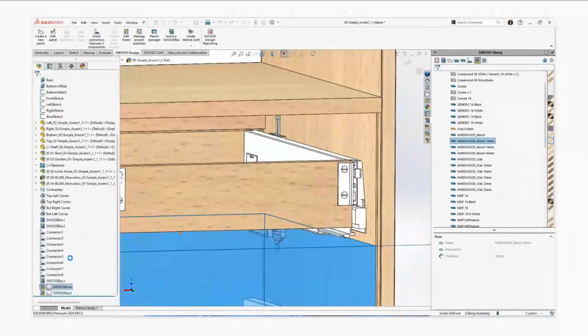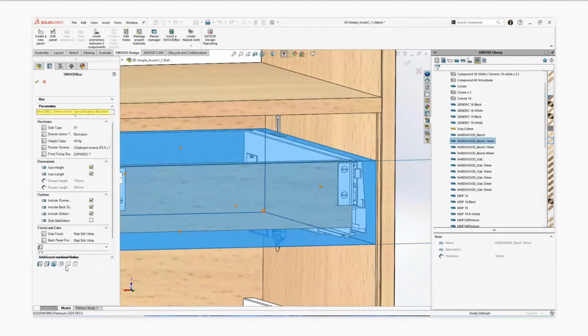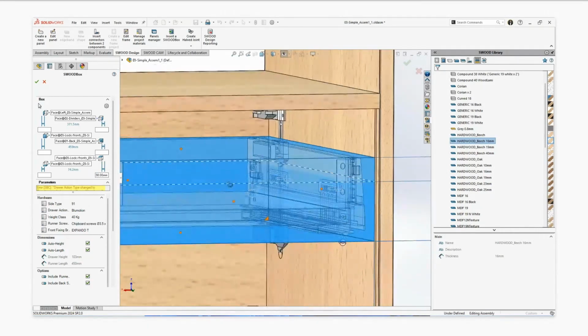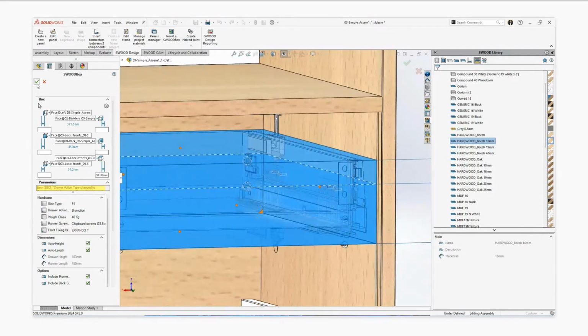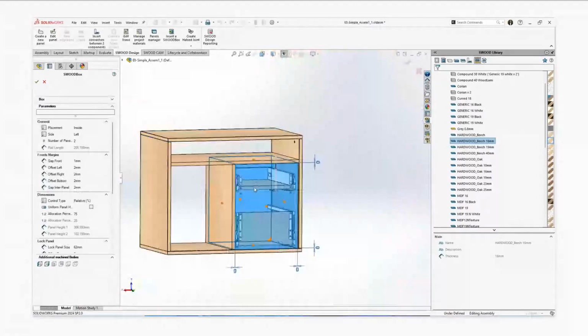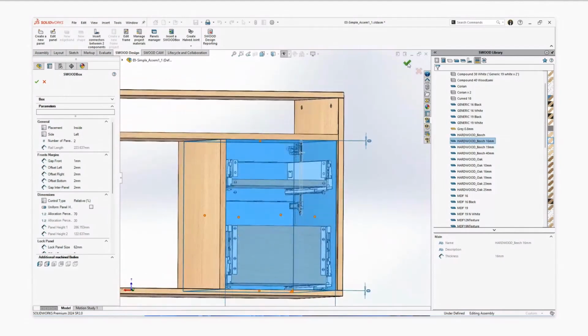That's the use of the 3D model. You can still visually see everything you need, and there is also some interference tool if you need. Just set an offset from the top to avoid having a problem. And here, as you can see, it detects there is not enough space for the Blum Legrabox range, so that's good. I just modify the front to increase the top front, so you can put some message to avoid some error, for example.